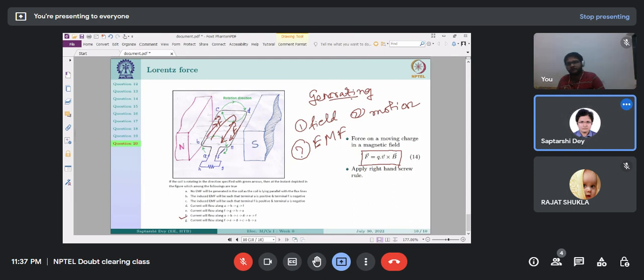And what will happen? See, this current is flowing like this through the resistor, so it is creating a voltage drop. So this will be plus, this will be minus, right? So this F terminal will be plus, A terminal will be minus. So F is positive, A is negative. This is the correct answer. And will there be anything else? Okay, current will be flowing from F G H A. F G H A, this one, this will be correct.